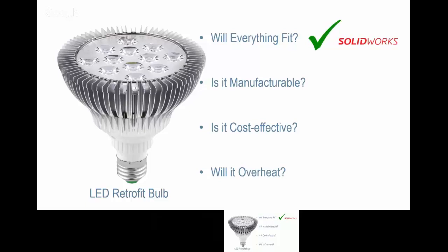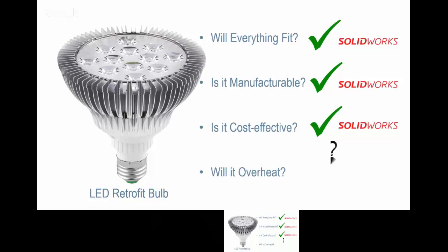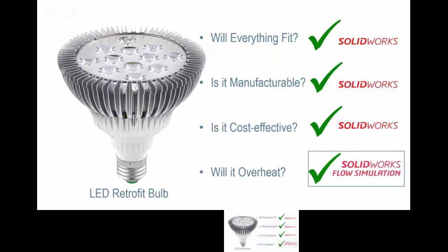So SolidWorks can help us with a lot of these problems. Will everything fit? Is it manufacturable? Obviously, SolidWorks can help us with all of these things. Is it cost effective? Are we using an appropriate material? We can even use things like SolidWorks Costing to help understand how much it would cost to manufacture it. But what about the question of whether or not it'll overheat? Can SolidWorks out of the box really help us with that problem? This would be a standard problem that you would use something like SolidWorks Flow Simulation to help answer.